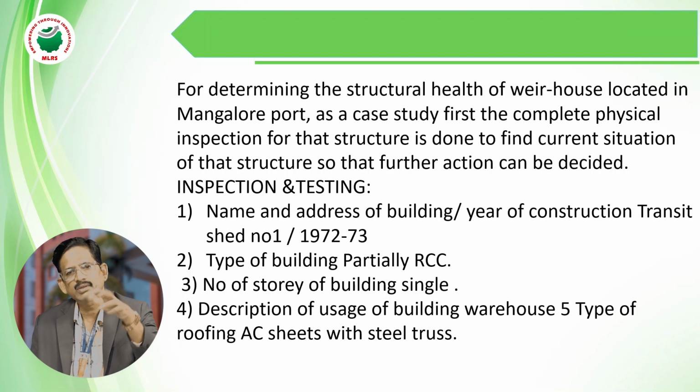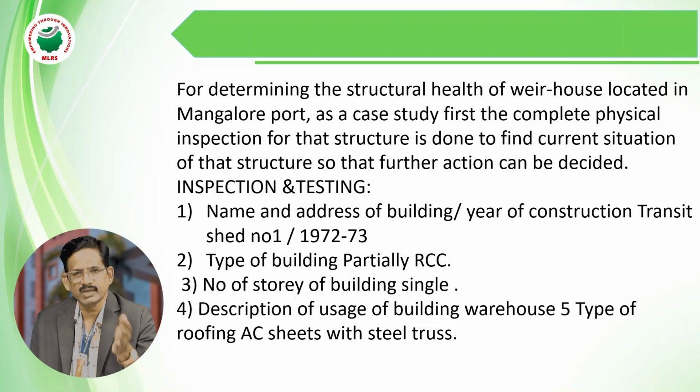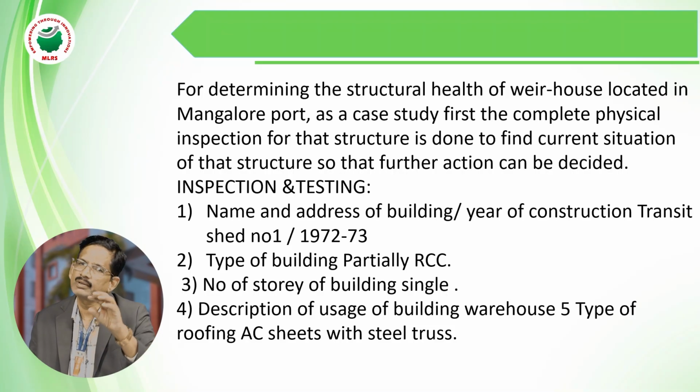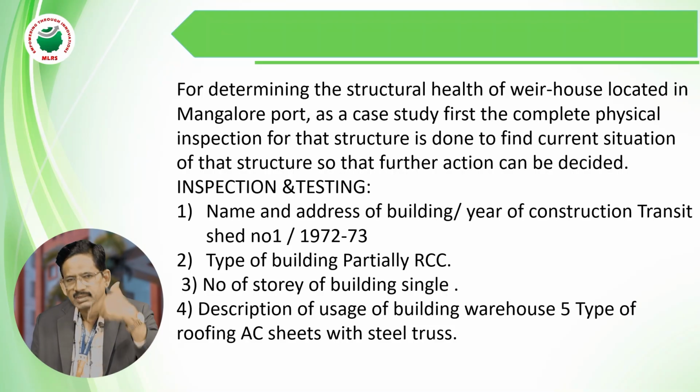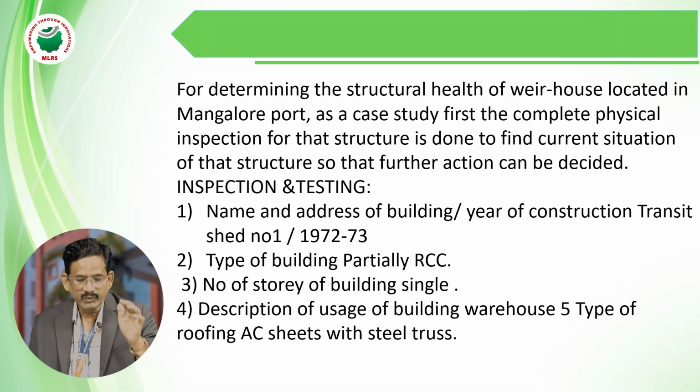After that, we go to the site and take photographs. In the plan, we see all the rooms and take photographs. If anything is observed, either cracks or leakages or any decay of the structure, we have to take photographs and verify physically. With the observation and clear inspection of the photographs, we have to conclude what the problem is, either leakage or slab expansion or anything else. The possible reason is to be determined based on the photographs and physical inspection.